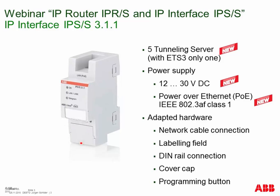The cover cap covering the KNX bus and also the low voltage power supply connection makes a safe insulation between any 230 volt wire going in parallel here and these connections. And the programming button, not visible here, has been adapted a bit. It's now easy to use a screwdriver, but your fingernail is also still possible to press the button.